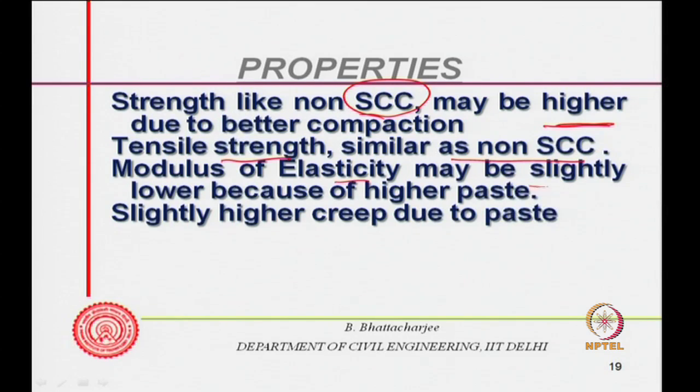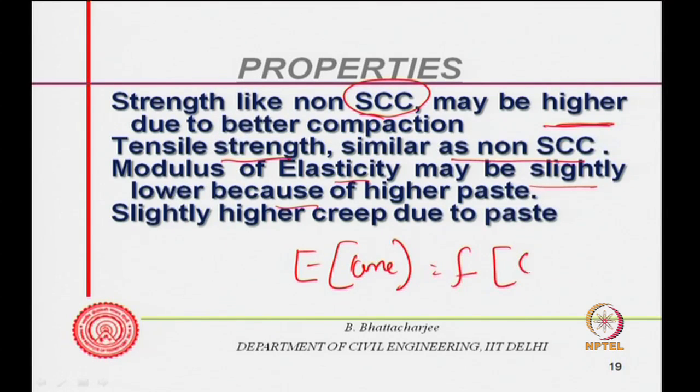Modulus of elasticity may be slightly lower because of higher paste content. Now, here is the modulus of elasticity. We talked about E of the concrete is a function of E of paste, paste volume, and E of aggregate and V aggregate.